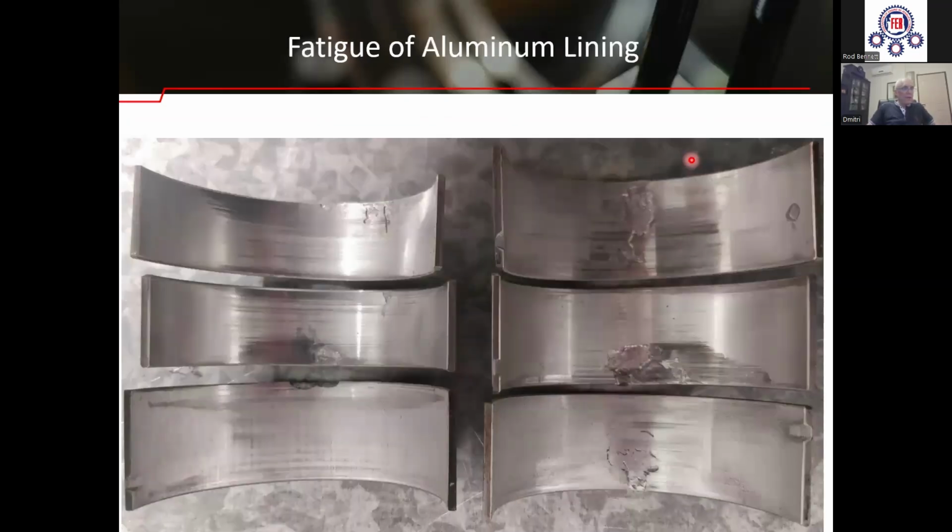If a bearing is edge loaded, the load is localized at a small area, and the specific load may exceed the fatigue strength of the material and cause its fatigue. You can see here edge loaded bearing with the fatigue area, also here and here and here.